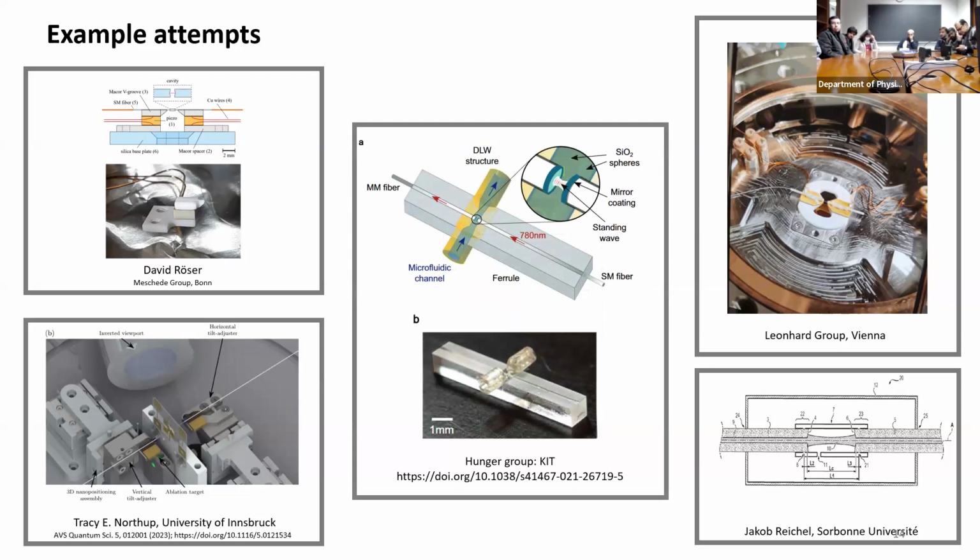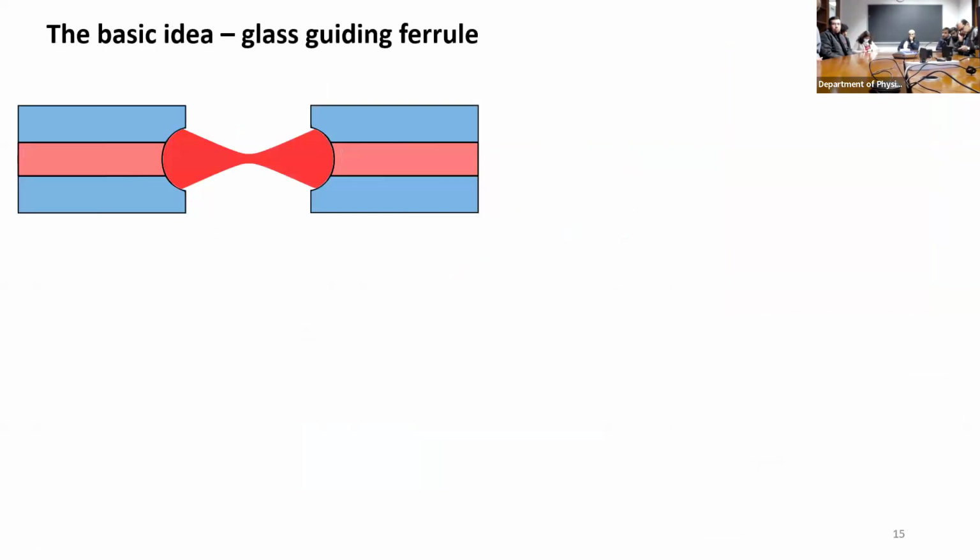Okay. But one thing I measured, spoiler alert, is that the fiber has a protective coating outside. When we prepare the fibers, we chemically dissolve the protective coating, but some of that dissolving is imperfect. So you may have a bit of material stuck on the outside, and the fiber radius increases at some point. This leads to the fiber sticking inside the core. So even if you don't have a good stable system, the fiber still has a bit of friction in the system, and then it may be accidentally stable. But that's something I measured in my system afterwards.